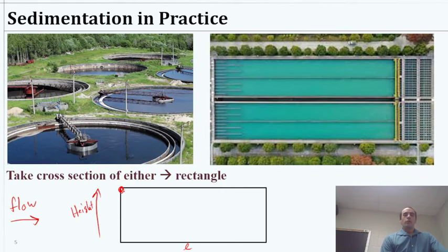And so essentially what we want is by the time water reaches the end here, we have to make the particle hit the bottom in order to be separated, because that way it sticks to the bottom. Whatever flow, usually we harvest water kind of from the upper area, but the flow of water still does have to go this way, right? So the water flowing through, if the particle doesn't hit the bottom before we've reached the end of what we've defined as a reactor, it's not necessarily settled.